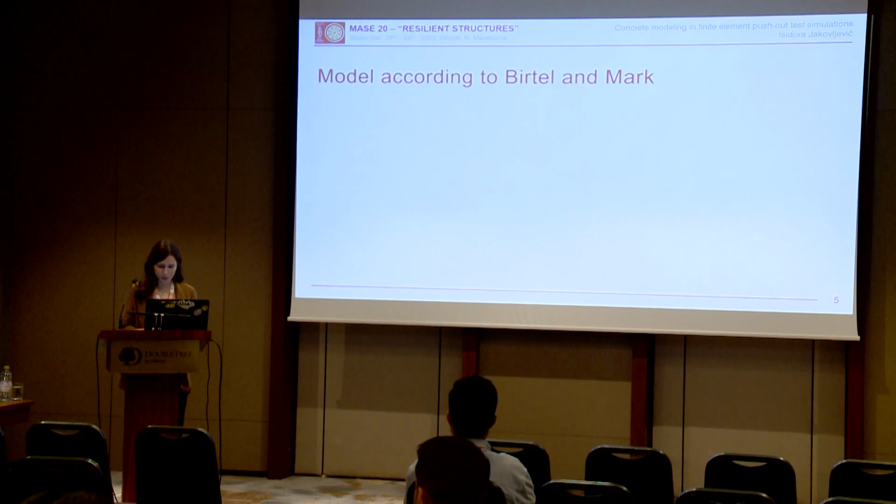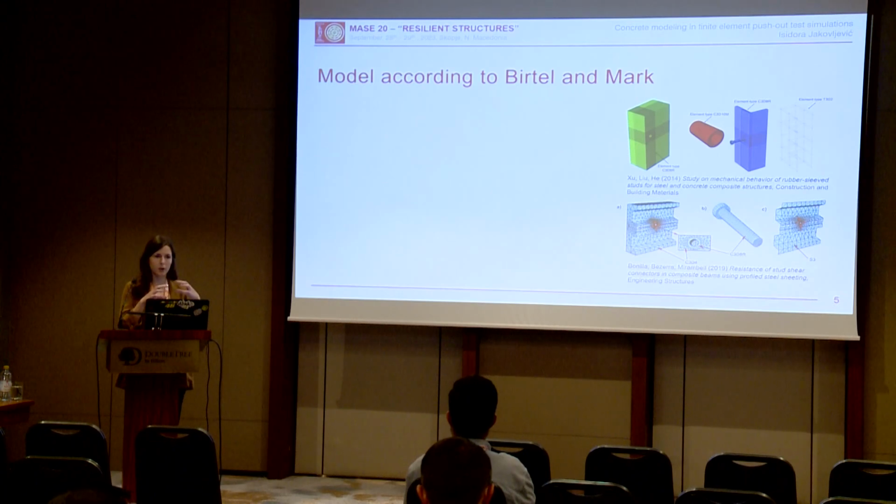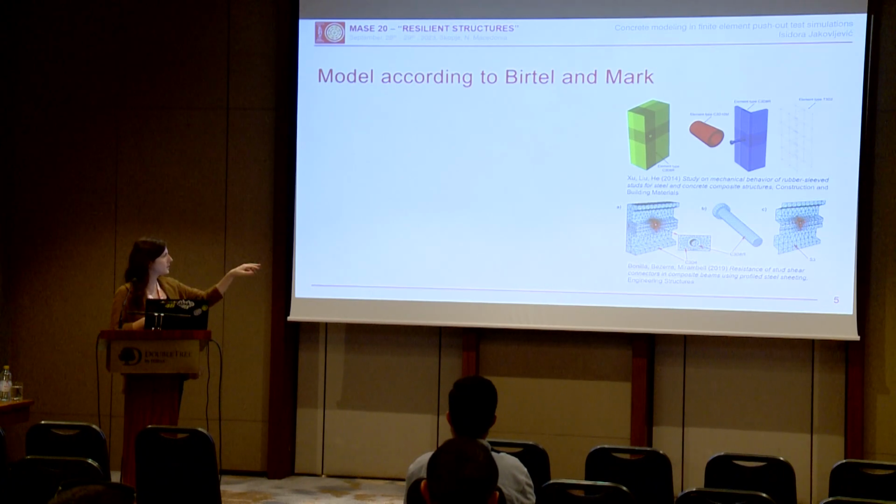So the first model is the one by Bertel and Mark. It was initially made for modeling the concrete behavior of reinforced beams, but it was also applied in some push-out tests, as presented here by some other authors. In both cases, we have headed studs. In the first case, it is in a solid slab with some rubber placed around the headed studs, and in the second case, headed studs in a steel-concrete composite slab.